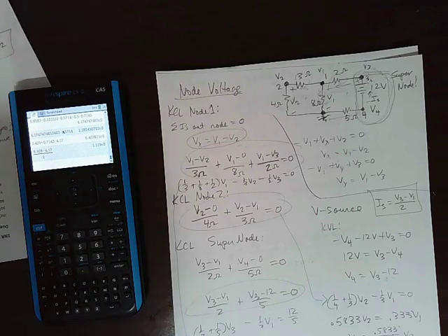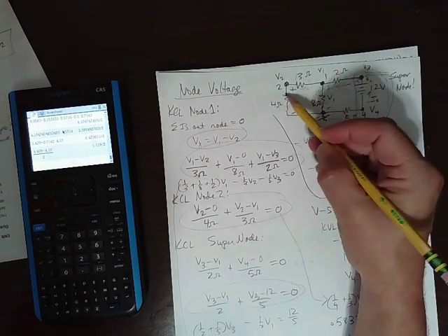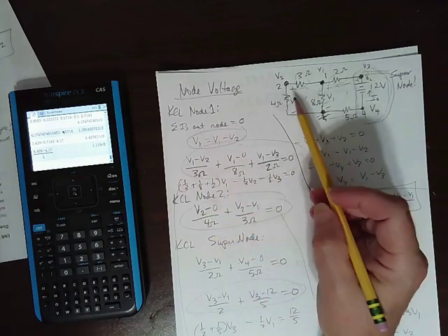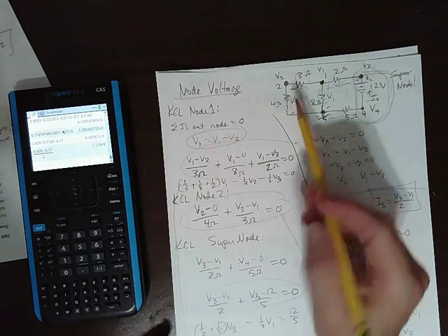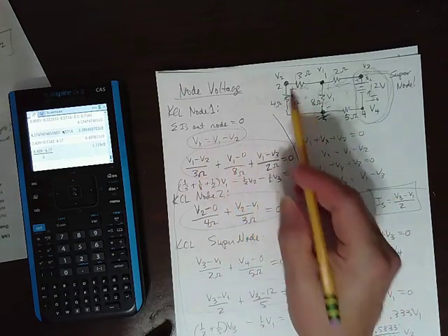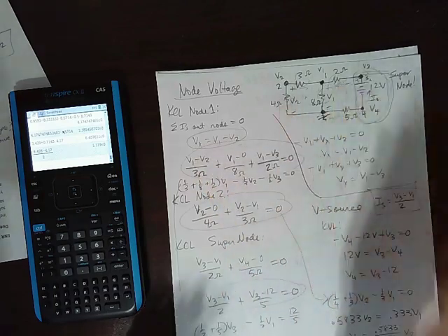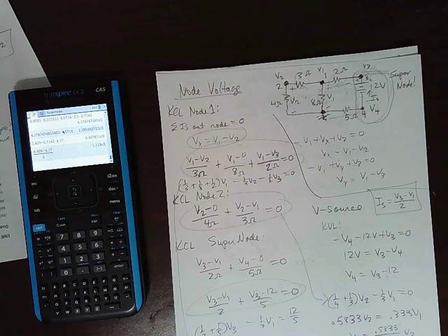I guess one thing to note is if you have a current source, what if one of these was a current source? Then the KCL equations become easy for that node because you don't have to do a super node, you just know the current. So if it was a 5 amp source, you could just put 5 plus or negative 5 if it's going the wrong direction. So when you're doing your KCL, if you have current sources, they make it easy. You just put in the number that the source tells you. Okay, I think we'll stop there. That one problem done many different ways kind of illustrated most of the things we need for this chapter or this module.